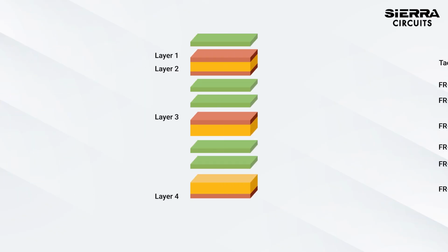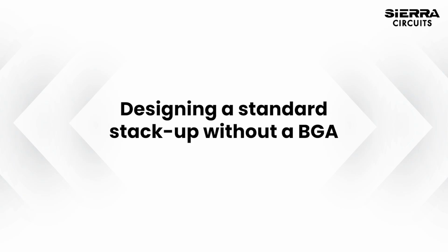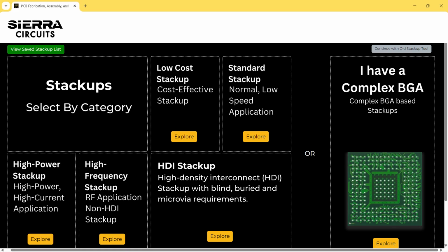Sierra Circuit's PCB Stackup Designer helps you design manufacturable buildups. It also has built-in calculators to optimize your stackup to maintain signal integrity. First, let's begin with a simple stackup without a BGA. To begin, select your stackup category.